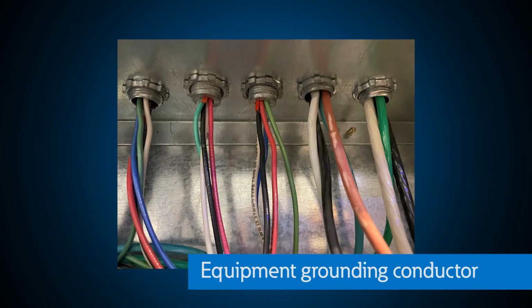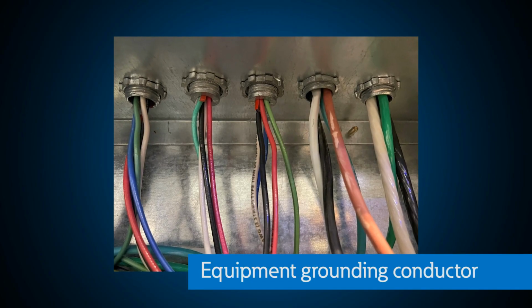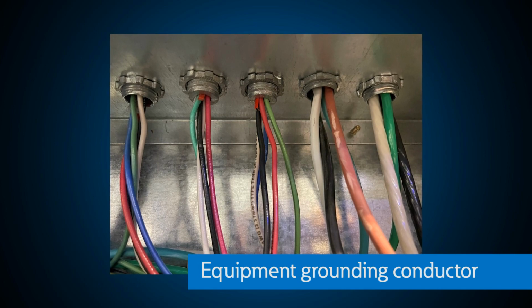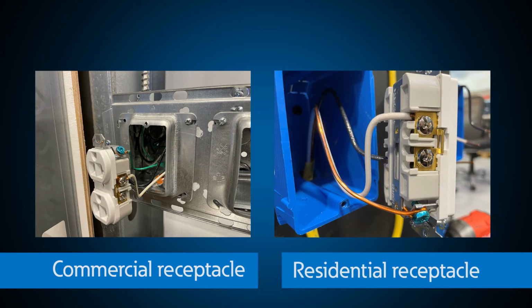Think of this as that bare copper conductor that you carry out to all of those loads. Or if you open up any receptacle, you'll see that bare copper conductor that's in the receptacle outlet. That is your equipment grounding conductor. We want that to be a low impedance, and we want that to carry fault current should a fault, a ground fault, occur in the system.